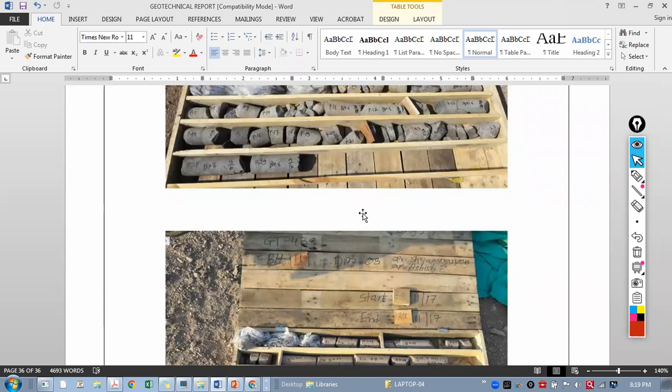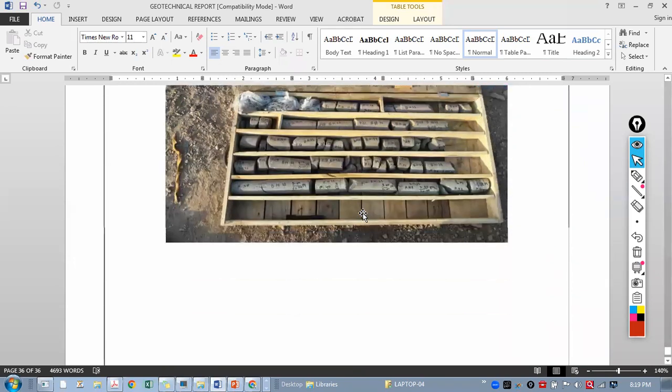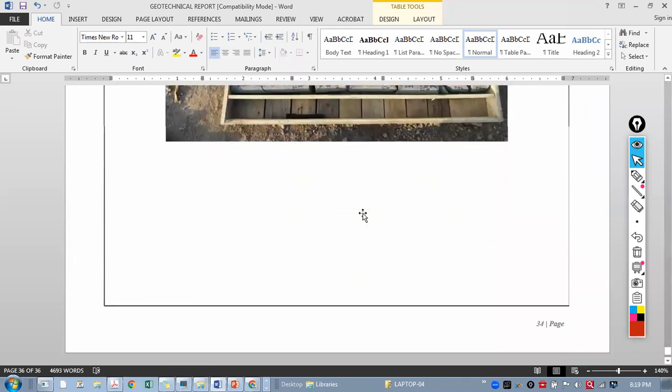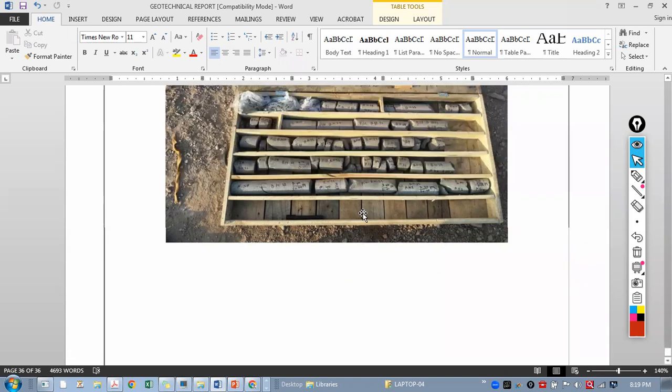So we are interested in going quite below the ground. So it is for major projects, generally tunnels. You know that we are drilling the tunnels, and then there is a hill, quite big hill actually. It may be 50 meters high, 100 meters high. So we are drilling from the top to understand whether there is a hard rock, so that we can drill that tunnel. And during the tunneling, we can decide to go for lining, concrete lining or not. Some tunnels are there without concrete lining also. You might have seen this.